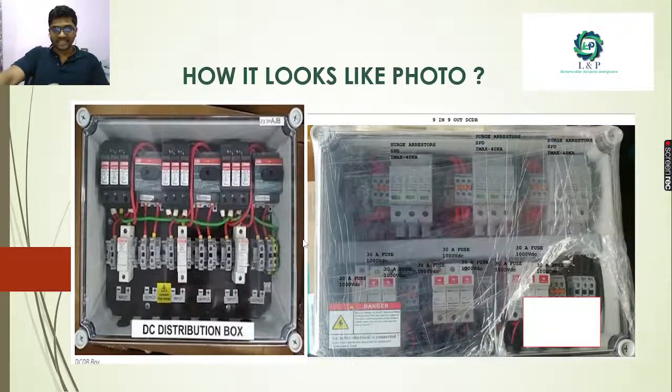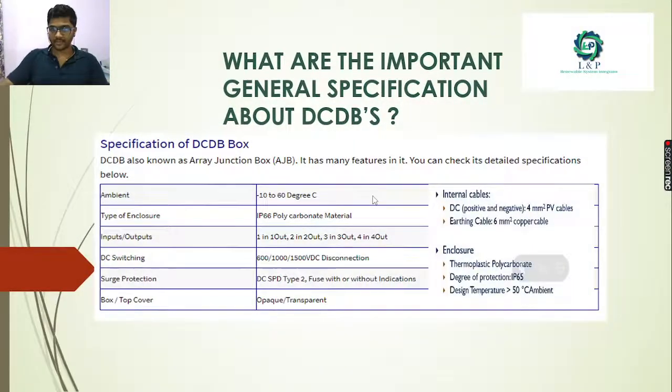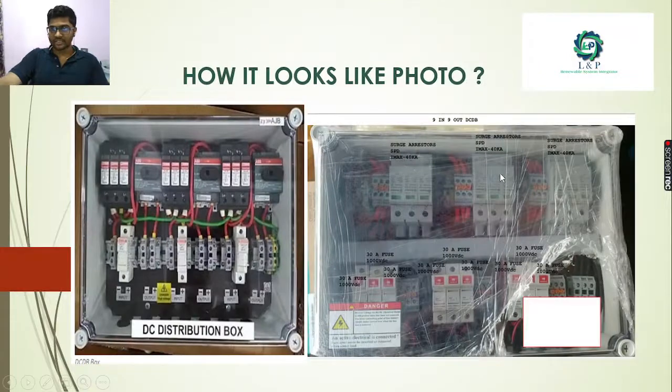See, this is an elaborated clear photo. Here we have surge protection devices, which are rated around 40 kiloamps. We are providing the fuse terminals with fuses as well. Normally we have 15 amp fuses. If the rating is high, we can go up to 20 amps. And we have many internal terminals for the wiring.